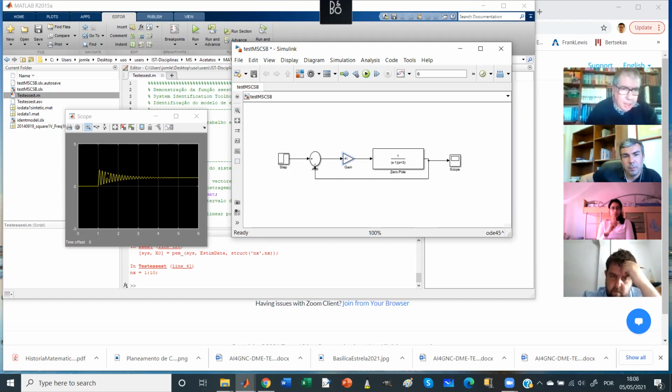So we could have said, instead of specifying K, I could have specified, I want the poles at some place. But I only have one gain. So with this gain, I can only change the poles according to that cross. They come one to the other, and then one goes up and the other goes down.